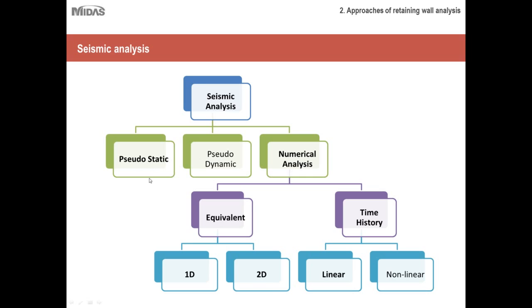But for now, you can just understand that pseudo-static is a set of formulations which considers the mass of the structure to be at rest and not in a dynamic state. It just considers the mass of the structure at rest, which would cause a certain amount of horizontal or vertical force onto the structure when excited under earthquake.